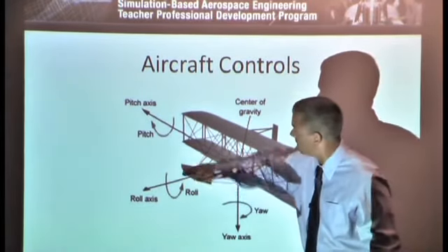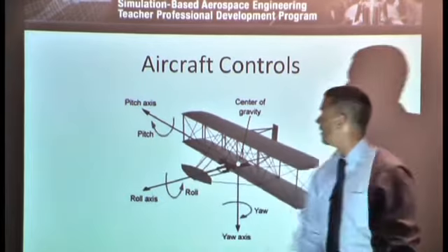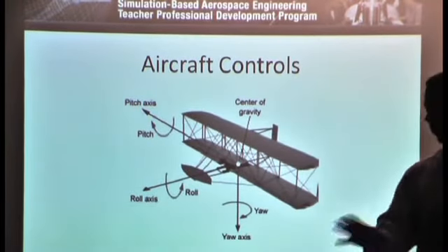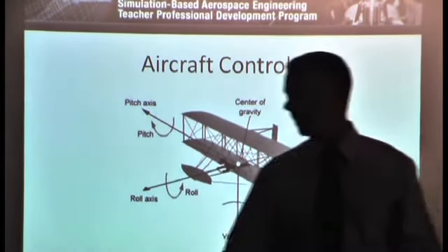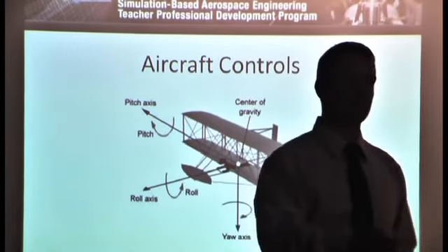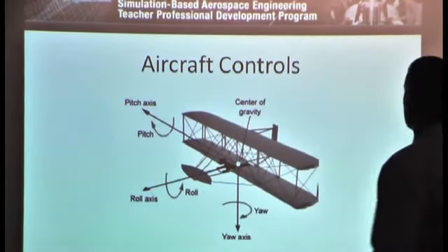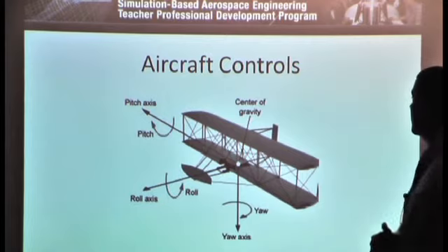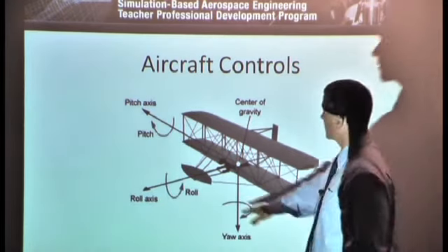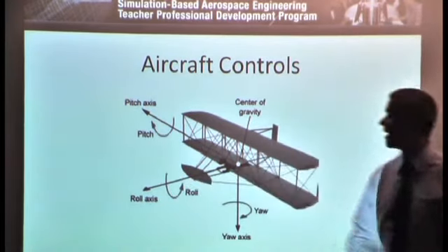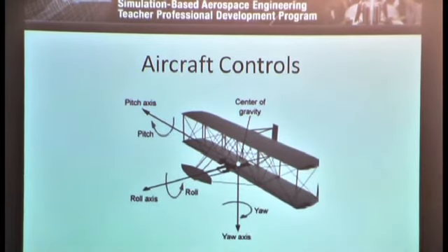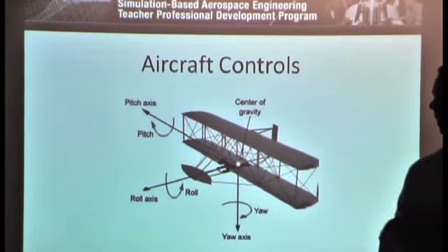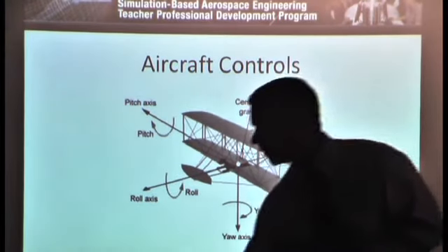Likewise, the roll was controlled by the wings or the ailerons in the front, which on more current aircraft you would notice are probably located on the wing section. And the pitch was controlled by the elevators, which are also part of this contraption on the original flyer that moved up and down as well. Nowadays there is the boom going out the back of the aircraft more often than not, and that's where the elevators are located.